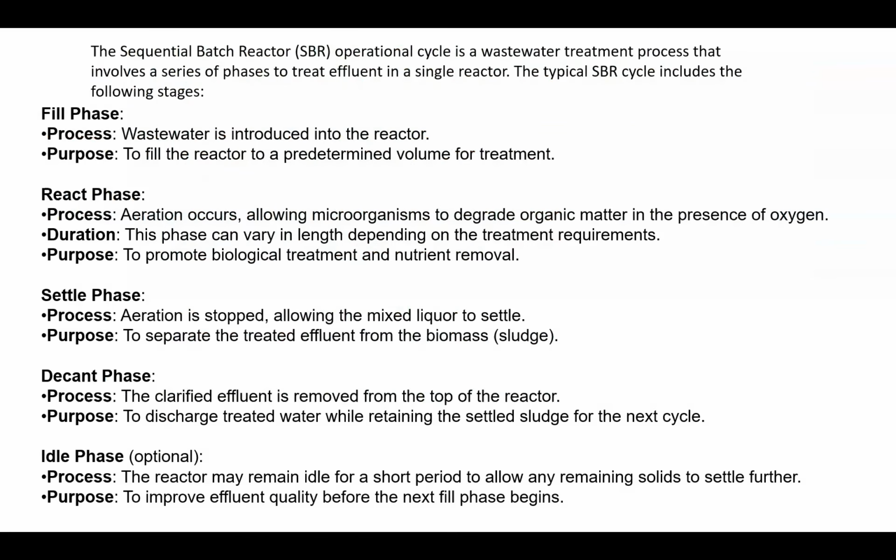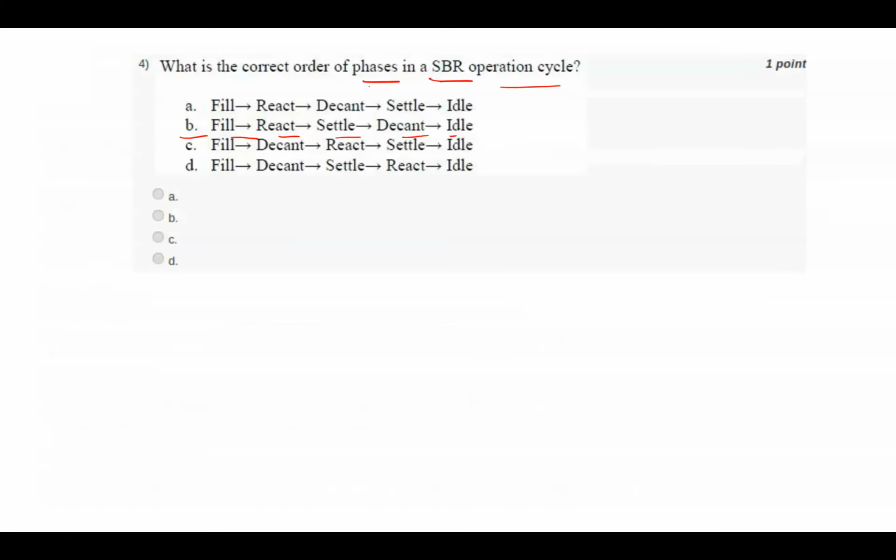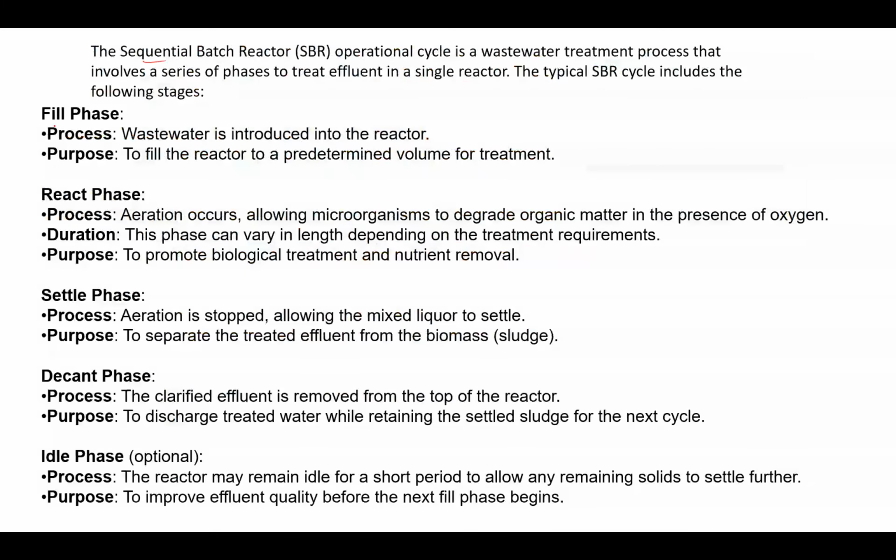I will explain. This is the sequential batch reactor operational cycle, and five phases are given. First is the fill phase, which means wastewater is introduced into the reactor.